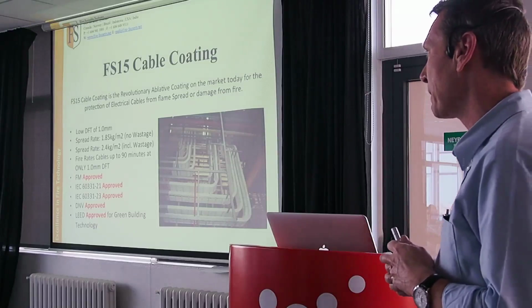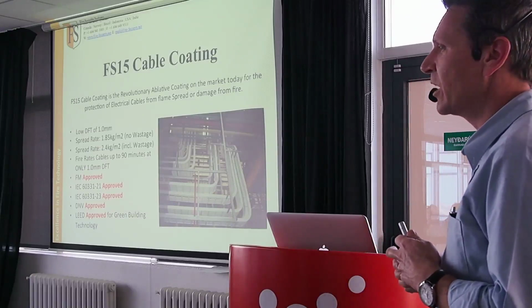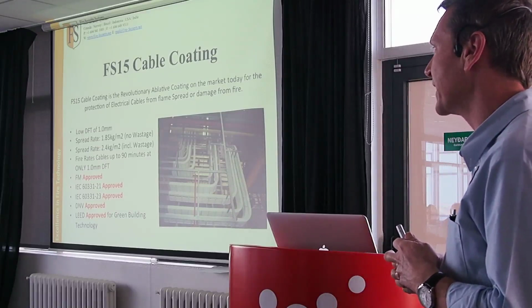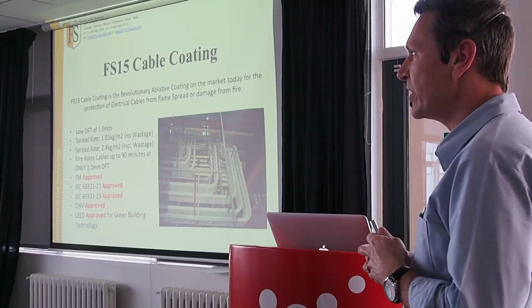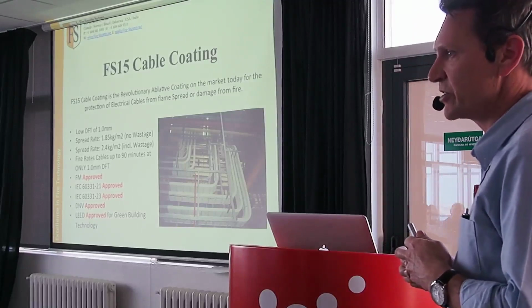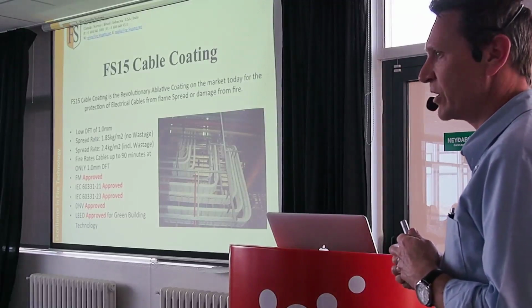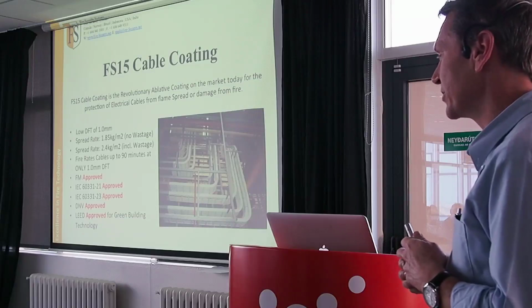We fire rate cables up to 90 minutes. Non-fire rated cables, emergency cable, emergency lighting cable, high voltage, low voltage, data cable, and various types of sheath, even silicone sheath, all we can fire rate up to 90 minutes after cure, with only 1 millimetre dry film thickness.